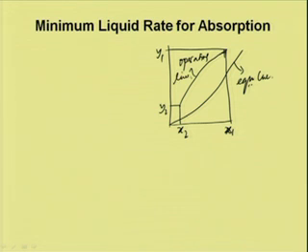If we work in mole fractions, both the operating line and the equilibrium line are curved. Obtaining a pinch point in this case is difficult, and we have to work with two different curves instead of a straight operating line. So, for convenience, we generally use the mole ratio X-Y plot instead of the mole fraction X-Y plot.